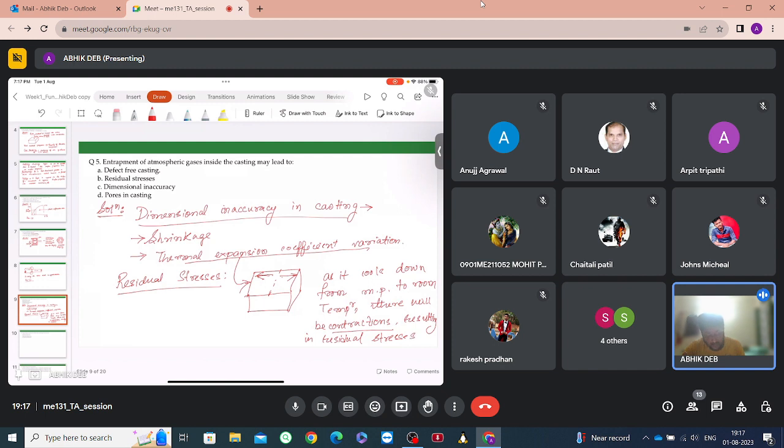so what happens in this residual stress? As a tensile stress is already in by default, it is coming into the component. So whatever ultimate tensile strength or yield strength it was supposed to undergo deformation or fracture, it will now undergo at a lower value of tensile stress. So that is a negative effect of tensile residual stress. So is it clear how this is coming?